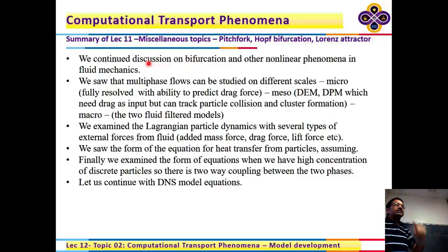So the questions that you are raising will hopefully become clear. There is some part that I still don't understand, why it doesn't give you the right pressure. But you will notice that the pressure is uncoupled from the velocity field. So when you're simplifying this, subject to the condition that the velocity field has Vr equal to 0, V theta which is non-zero, and Vz equal to 0, but V theta is a function only of r. For one-dimensional flow, that is your velocity field. V theta component is non-zero, but it changes only in the radial direction. It doesn't change in the angular direction or the axial direction.